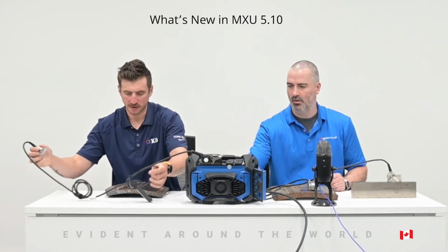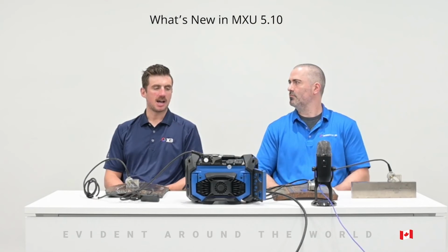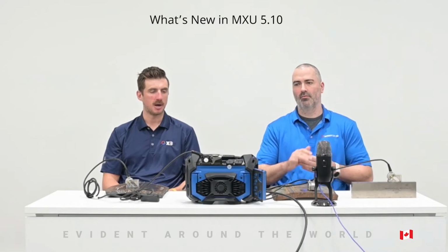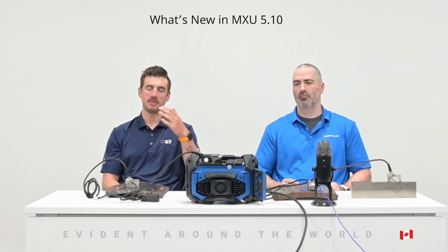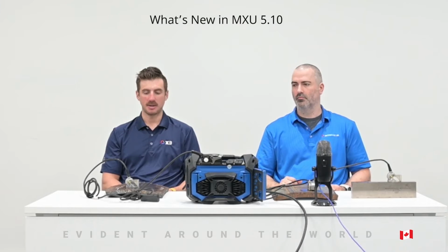Thanks, Stefan. The final feature we're going to talk about today is the new weld overlays for phased array with COD. Previously, we had the zone of interest in TFM, which was curved around the shape of our part. And in phased array, we have the different legs, which are also curved in order to demonstrate the thickness of the part for each leg. But now we're going to have the actual weld overlay, which is going to be repeated in each leg and also is going to adapt in order to meet the sound path in that same part.